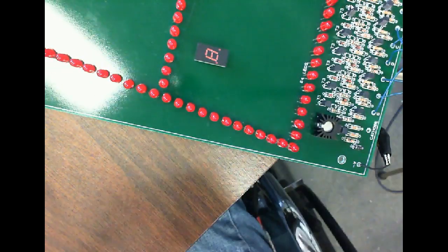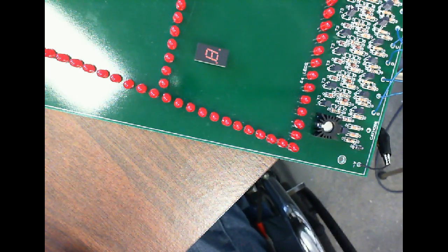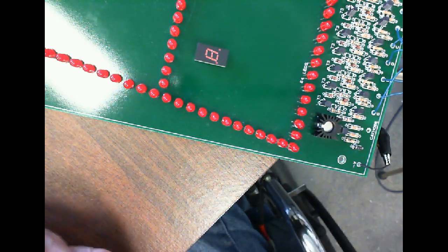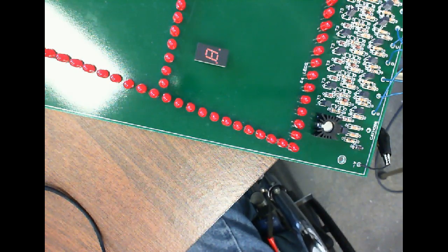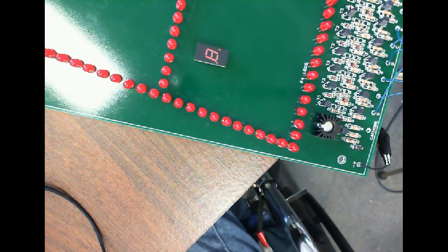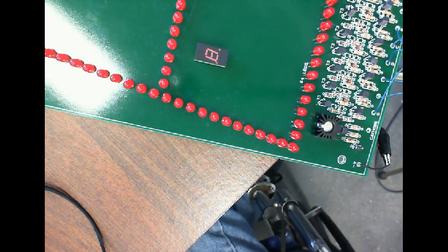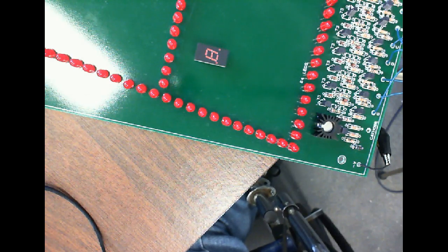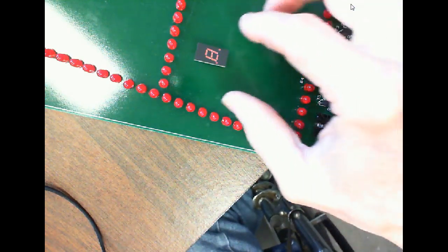The decimal points are not considered to be part of the 7-segment display, and decoders don't support the decimal points. You have to decide when the decimal point turns on or off. Even your calculators use this same feature. They use a 7-segment display, but instead of using LEDs, they're using LCDs, liquid crystal displays, and they have to be backlit.